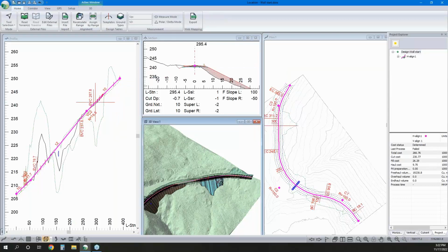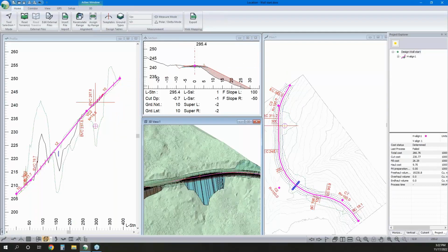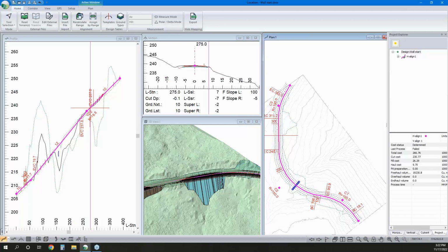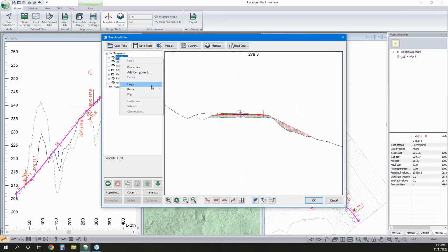And let's take care of this section here next. So to start, I'm going to look at using either our gabion basket or block template. We'll use it kind of as a gravity wall with a batter on it. But then we'll switch what we use there and use that new template that we showed in the introduction. So templates, we use that as our basis again.